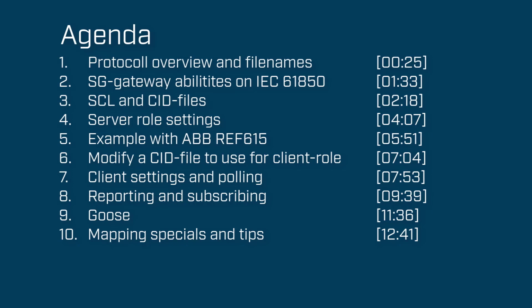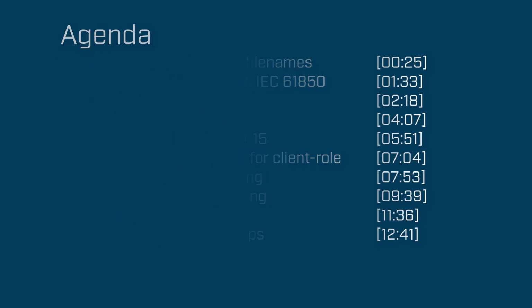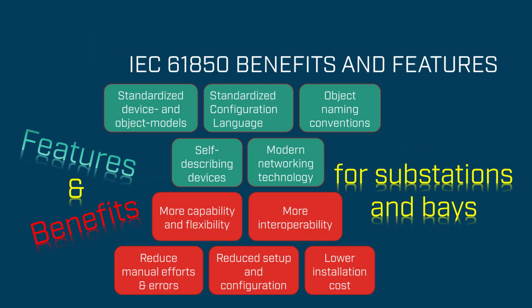IEC 61850 is an energy protocol that supports quality and timestamps with millisecond resolution using UTC. It contains a whole bunch of protocols and standards, integrated into one big thing to include all kinds of solutions for any grid communication topic.